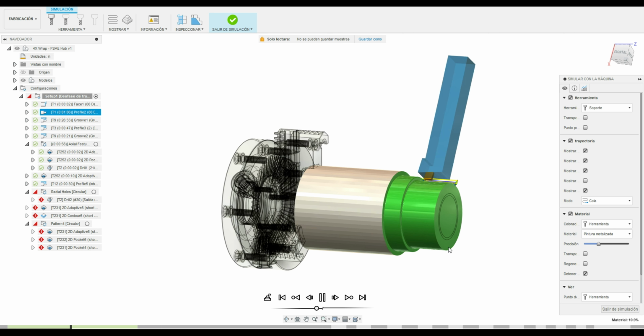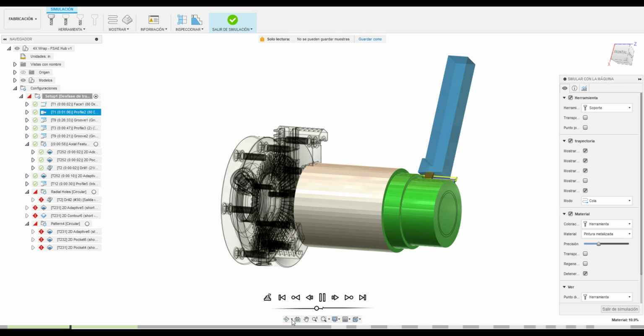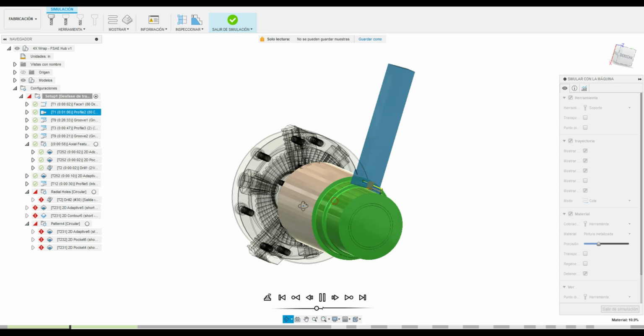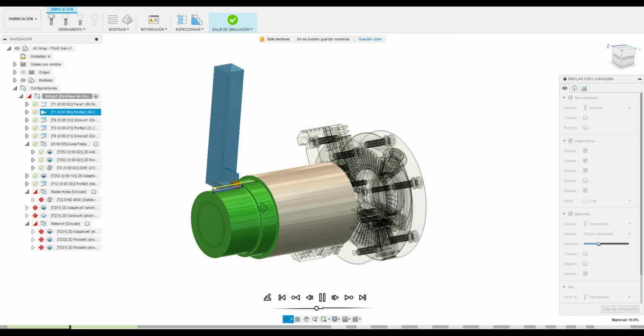Now the process moves into grooving operations, defining functional features such as retaining channels, O-ring seats, or component interfaces. Each groove is created with specific tooling parameters, maintaining dimensional tolerances often below 1/10 of a millimeter.